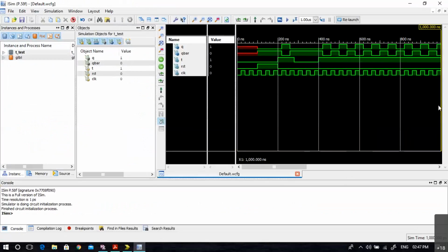You can see here now, when reset is 0, I have shown you the other earlier problem there. We can club reset and clock together inside the sensitivity list, and the simulator will support it, but the synthesizer will not support it later on because it becomes a mixed type. That is why I have retained it as it is. I will not change it later on either. Now T is 0 here. Now reset is also 0. That is why Q is X there.